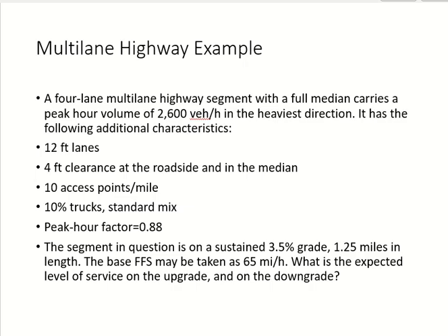So we have to do it for both directions. You did something similar in the highway course as well when you were designing the curve and taking the gradient. You do the same thing, right? The gradient is upward in one direction, so it is downward in the other direction. So if you take the entire highway, you have to take both. But again, going back to my point, they are saying do each direction separately. They did not say, okay, do it for one direction, multiply by 2, do it for the whole highway. We cannot do it like this. Clear? Even for level or rolling terrain.